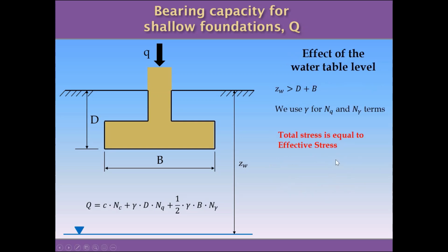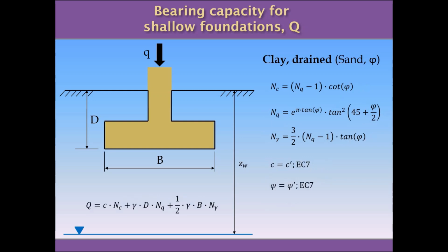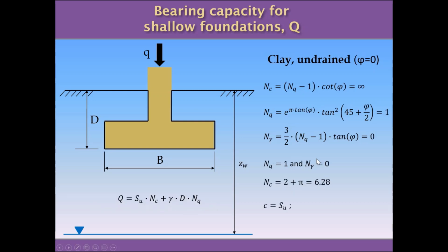Now, to end this video, we're going to see 3 different cases, taking into consideration the different positions that the water table can have. And I have to add, regarding the other 3 cases we've been discussing, in all these cases we have been discussing different types of soils. We have considered that the water table is far from the foundation, so there is not any water involved, and for this reason we didn't mention anything about this gamma, which is the dry unit weight for every case.